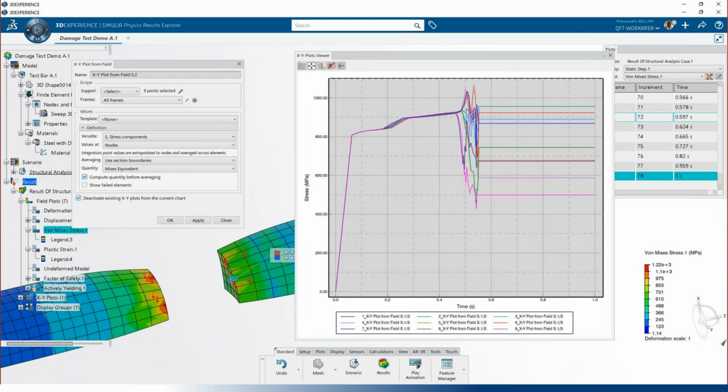And here also you can see the real damage curve. As we saw before, the elastic portion plotted on some of the points near the breaking point. So here you can see the elastic portion, you can see the plastic portion up above, and then the release of the damage, the third portion that is going down, and finally the break of the material.